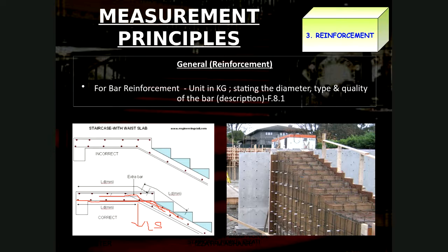The bar that is installed, I rub it again, you can see the bar that is installed along the way inside the staircase is considered as the bar inside the staircase, like this one. This is inside the staircase, but you can see the bar inside the staircase is overlapped with the bar inside the landing slab. That is the principle of the design that I would like every student to understand.